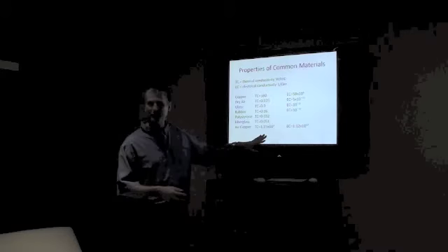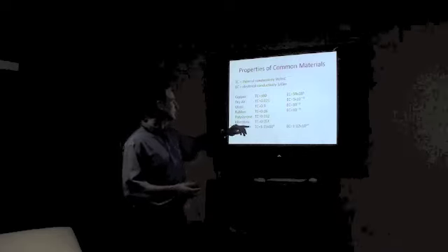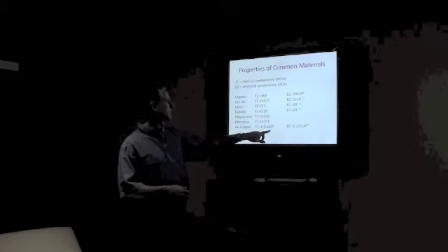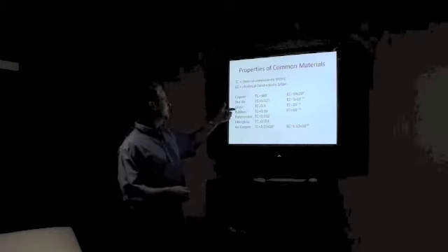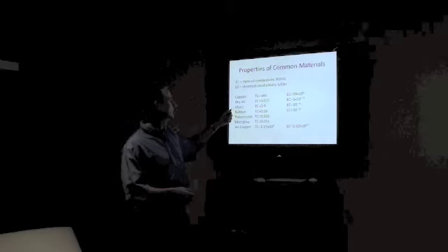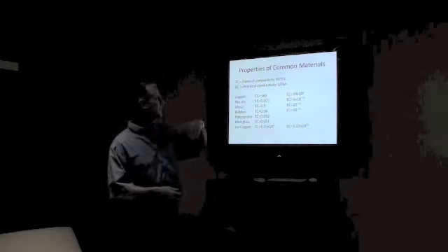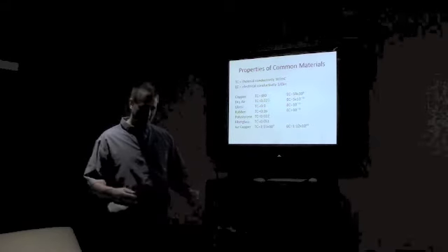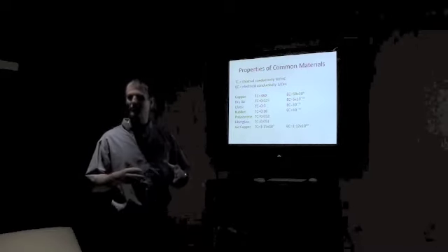Whereas in the thermal system, those same two, a really good thermal conductor and a good thermal insulator, it's only about 15,000 times better. And some substances, such as glass, we use it as an insulator, but it's only maybe 400 times better than what we're calling a really good conductor. So the range of materials for thermal insulators and conductors is a much smaller set.